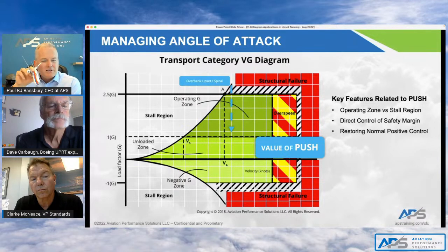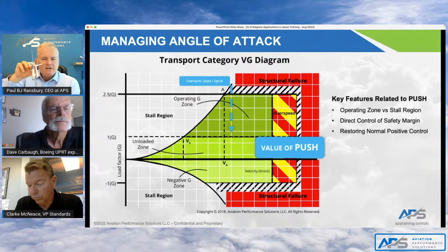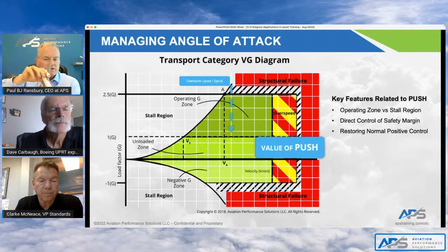So it's making it worse by pulling. So we want to unload. How much you unload is going to largely depend on how steep you are. Not a bad practice to think about targeting back down to the unload region, because remember, in this scenario, especially at high airspeed, you want to start unloading, managing energy and drag, and you want to start rolling the airplane.